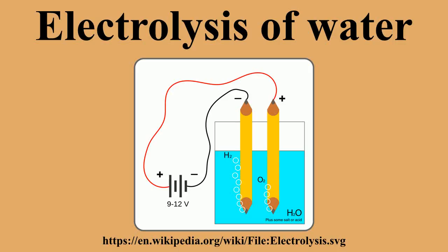Efficiency. Industrial output. Efficiency of modern hydrogen generators is measured by energy consumed per standard volume of hydrogen, assuming standard temperature and pressure of the H2. The lower the energy used by a generator, the higher would be its efficiency. A 100% efficient electrolyzer would consume 39.4 kWh per kilogram of hydrogen, 12,749 joules per liter. Practical electrolysis may consume 50 kWh per kilogram, and a further 15 kWh if the hydrogen is compressed for use in hydrogen cars.